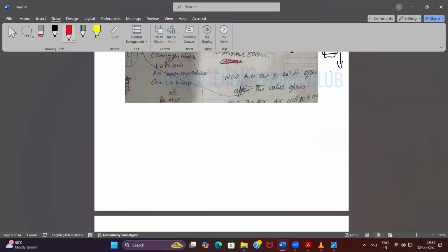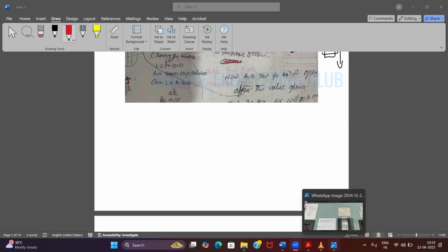So what you're asking here is, your ship's critical RPM range might have been 60 to 65 RPM. In that RPM range, your governors are designed to give more fuel to cross that RPM faster, because vibrations will be very excessive. This is for your engine, not for all ships. In my ship there was no critical RPM.